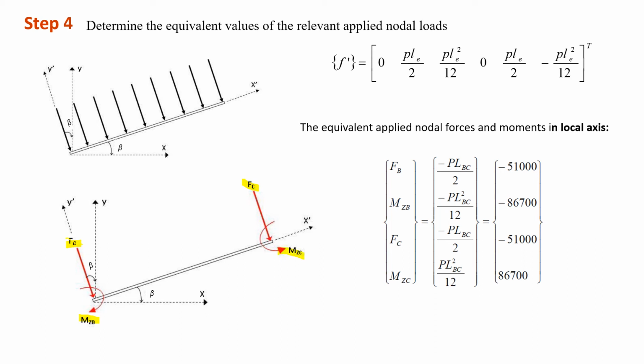They have no force in the local X direction, as the local force in X is always equal to 0 from the equations. That's why we only have local force in the local Y direction and moment in the Z direction. Next, we have to resolve these forces into the global direction, meaning that we have to resolve into the Y direction, as well as into the X direction.